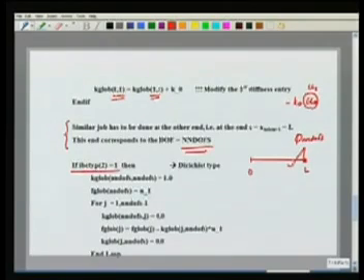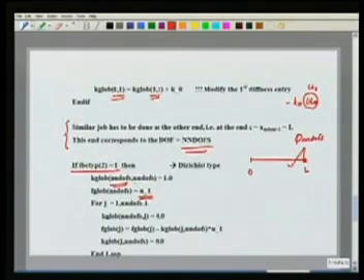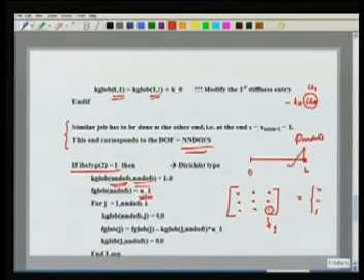So again, what do we do at the end 2? If my boundary condition is the Dirichlet type, then I specify what is the known displacement that has to be applied here, that is given by the value 1. So again, I go and set the diagonal entry here, this diagonal entry which corresponds to n and offs, to a value 1, and I will set the last load vector entry to the value u1, the specified value 1 at this end. So again, the rest of the column entries in the last row I am going to set to 0. So the last row is going to give me the value of the end deflection is equal to the specified value, and again what do I have to do in order to obtain symmetry?